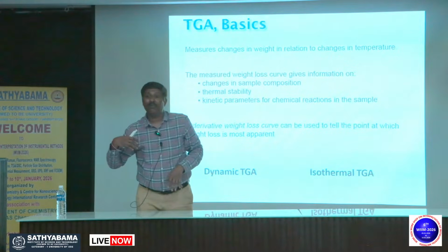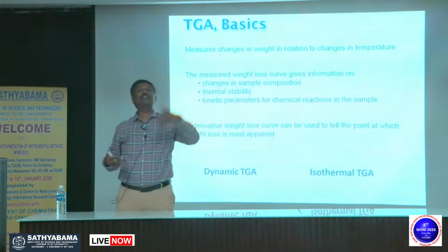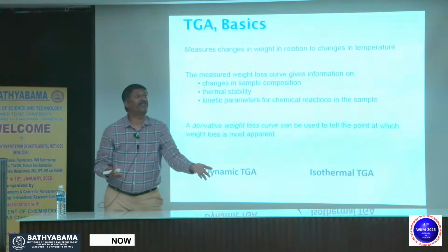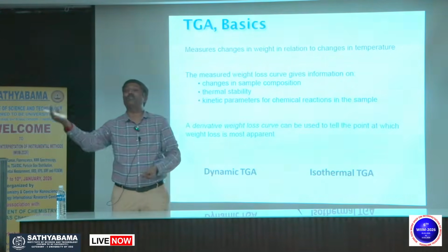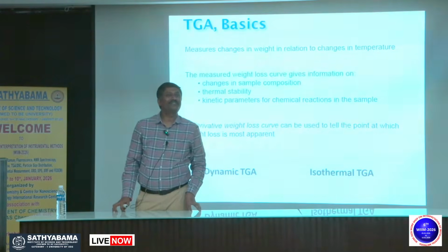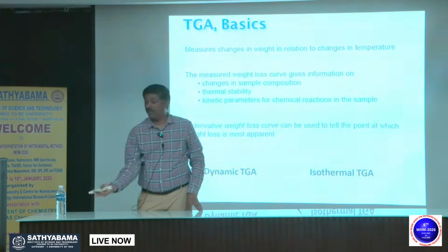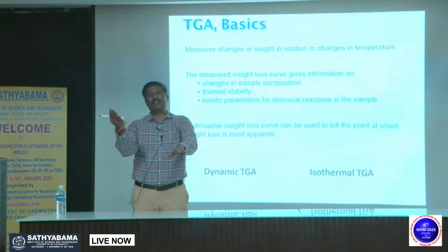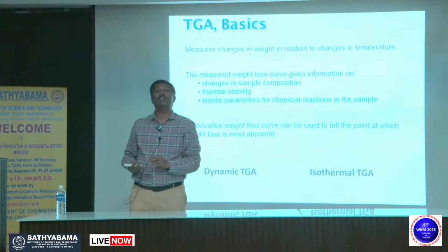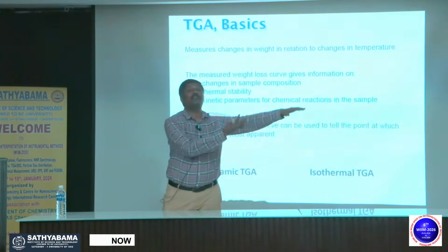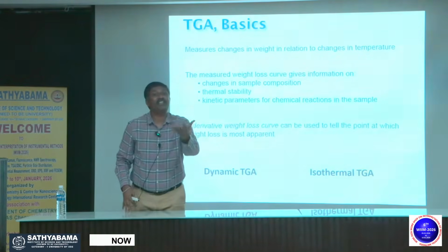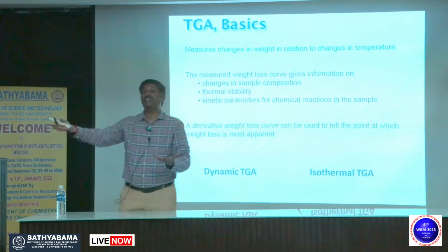Weight change. So if we know weight change versus time, kinetics will come in picture. Weight changes with temperature, thermodynamics will come in the picture. These are the few experiments where you can do thermodynamics and kinetics together. You getting my point? Temperature increased, weight decreased. Now, how fast or how slow it is decreasing, or how long this sample is sustaining, that will tell you about your materials. Stability of your material against the temperature.